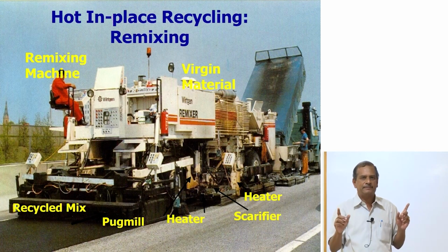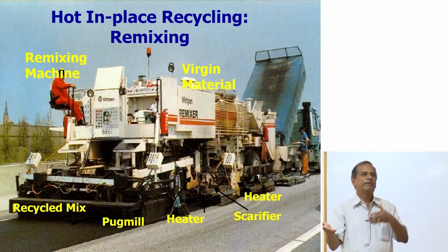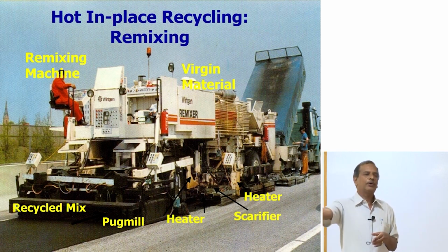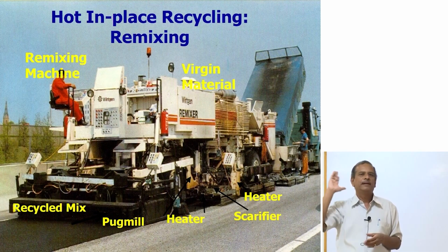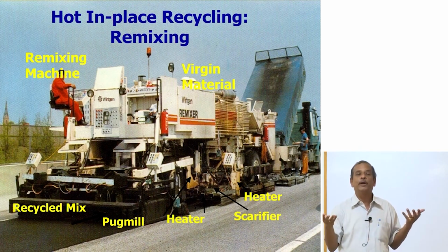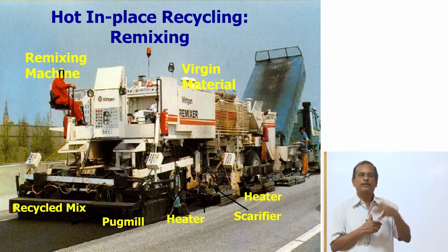Life cycle cost analysis, road asset management, pavement preservation. These are the techniques that you have to adopt when you graduate. So construction is one hand, maintenance is on the other hand. Maintenance challenges are like a doctor diagnosing a disease. You have a road that is deteriorated, for example, the campus roads. These roads were constructed in the year 2009. Now they are 10 years old. Now what should I do? So as a civil engineer, you should be able to tell, should I recycle? Should I use a modified binder? Should I adopt white topping?